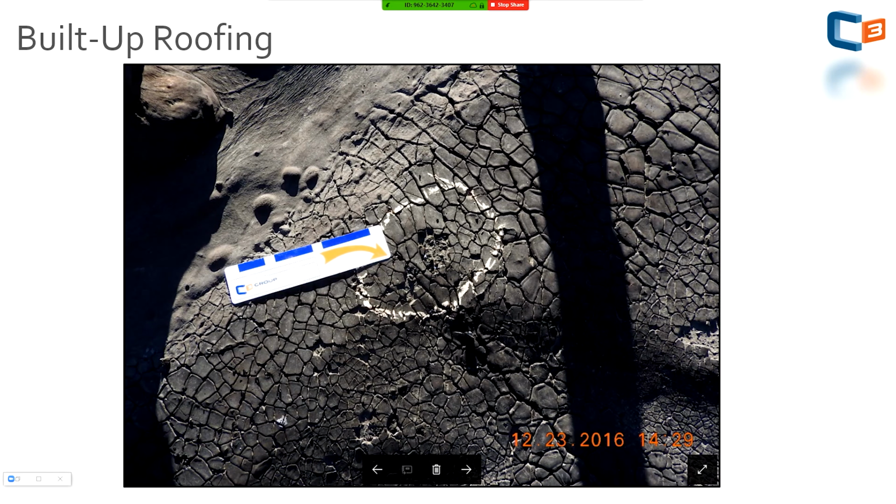If you don't have ballast sitting on the roof, this is a flood-coated roof. This is actually a coal tar pitch roof, which is an older type of tar used instead of modified asphalt on the newer types. And it actually popped off the flood coat. In this case, we had a bruise. You can see where I have that circled area. It has a little concentric ring where it impacted and just spalled off that flood coat. So here you have to ask yourself, did it just damage the flood coat or did it damage the reinforcement ply? Sometimes, if we can't determine what it did there, we'll send this in for desaturation, which is basically where they use a vapor degreaser and remove the asphalt or the coal tar pitch. It just exposes the reinforcement layer. You can tell if that was fractured or stressed, and it might lead you to different repairs or replacement.